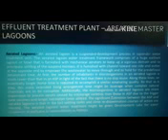At first, the population of microorganisms in an aerated lagoon is much lower than in ASP, because there is no sludge recycling. Therefore, a significantly longer residence time is required to achieve similar effluent quality. However, this longer residence time may be leveraged when complex organic chemicals are to be degraded. Also, the microorganisms in aerated lagoons are more resistant to process upsets caused by feed variations than those in ASP, due to the larger tank volumes and lower loading rates used.